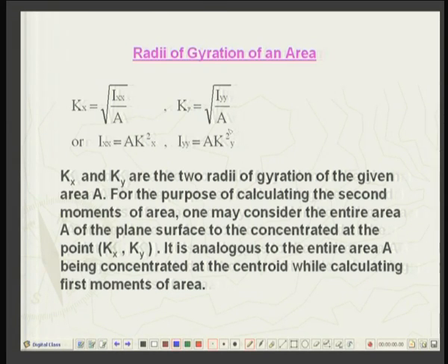Now, what is the physical significance of kx and ky? For the purpose of calculating the second moments of area, you can treat the whole given area as if it is concentrated at a point whose coordinates are kx and ky.